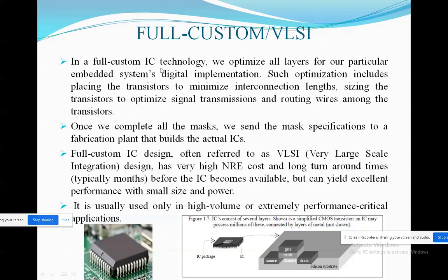In a full customized IC technology, we will optimize all the layers of our particular embedded system digital implementation. Such optimization includes placing the transistors to minimize the interconnection length, sizing the transistors to optimize signal transmission, and routing wires among the transistors.